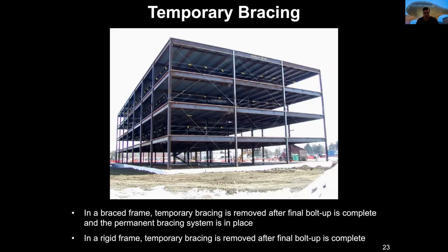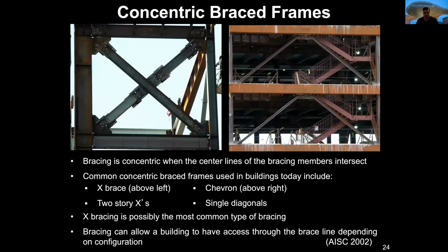Usually in brace frames, temporary bracing is removed after the final bolt up is complete. The building is bolted, and after it comes a final bolt to secure all the elements, and then it's possible to remove those elements. There are several types of framing elements.